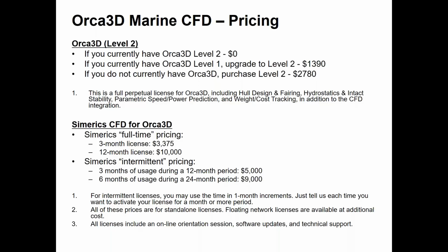The CFD pre-processing that Larry demonstrated is part of the Orca3D plugin, specifically in the Level 2 option. As Larry said, if you've created your hull model using just Rhino or even imported it from another NURB surface modeler, that's fine. You can use all of the functionality of Orca3D, such as real-time sections and hydrostatics while you edit the surface, lines drawings, and offset tables, hydrostatics and stability calculations, parametric speed power tools such as Savitsky, and so forth. You can use all of those Orca3D capabilities on your hull model no matter where it was created. And of course, you can use it as input to the Orca3D CFD pre-processing.